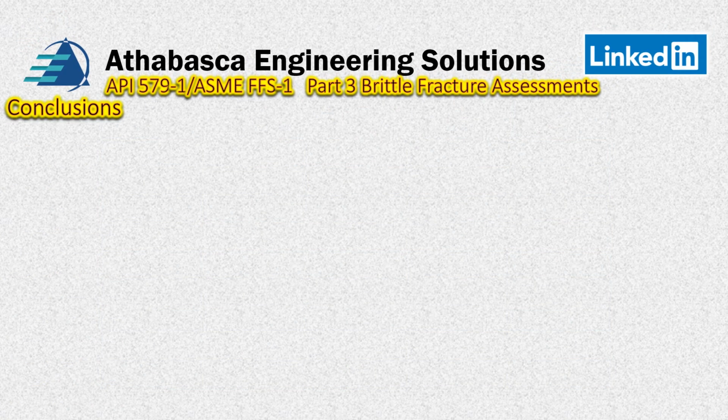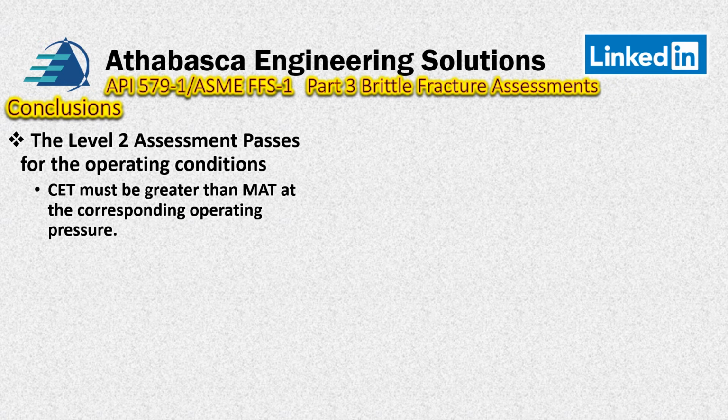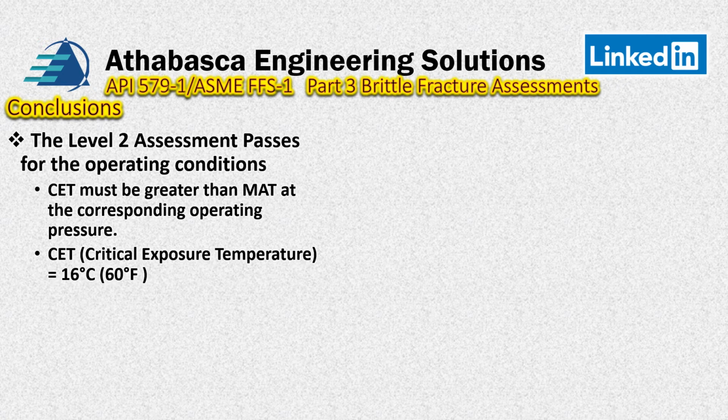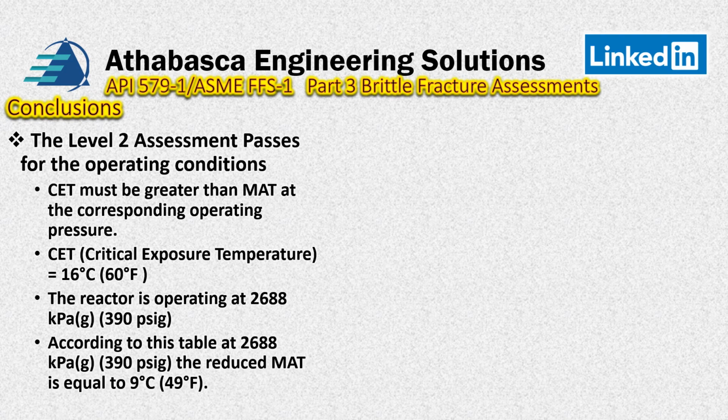Quite a few conclusions here to make. So the level 2 assessment, good news, we pass the operating conditions. But there's a few things to keep in mind. Remember that the CET, the critical temperature, must be greater than the MAT, and so for the corresponding pressure. So remember, we just did a pressure curve. So we know that our CET is 16 degrees centigrade. And so our reactor is at 390 psig or 2688 kPa.